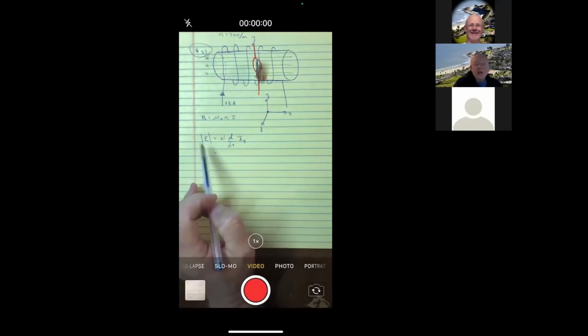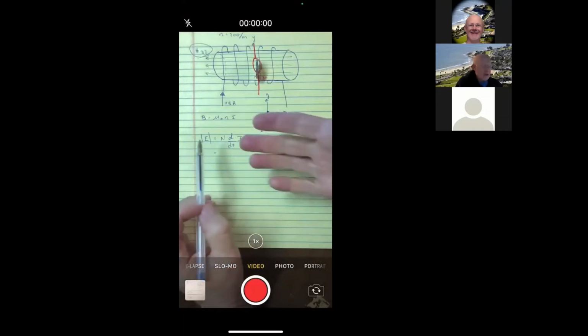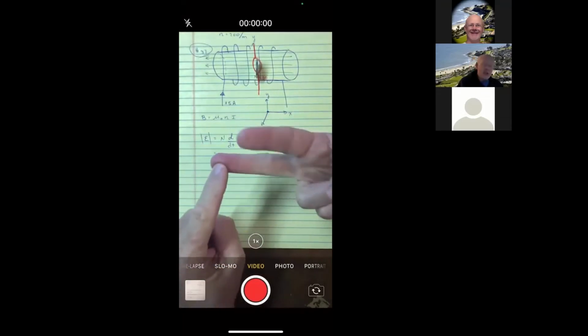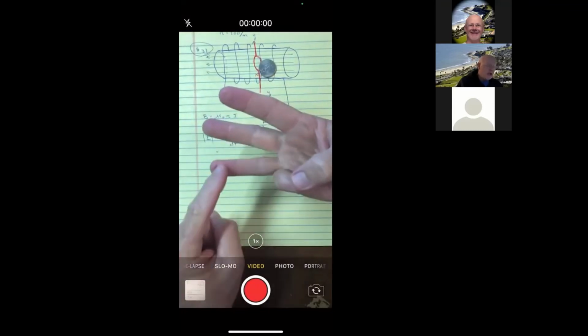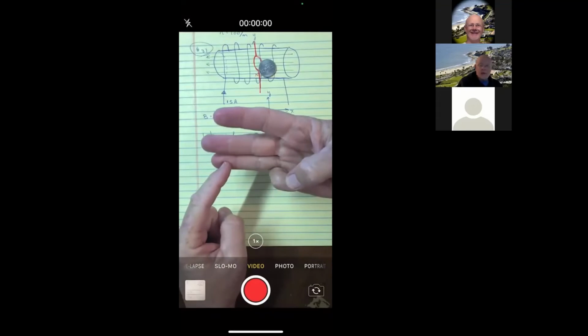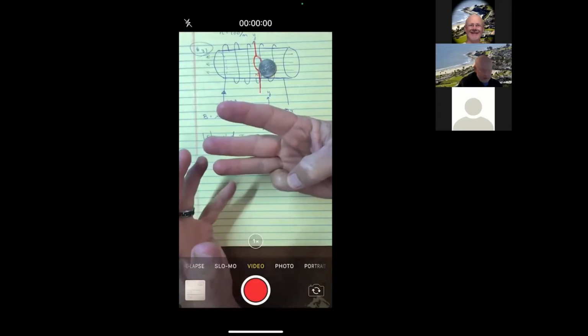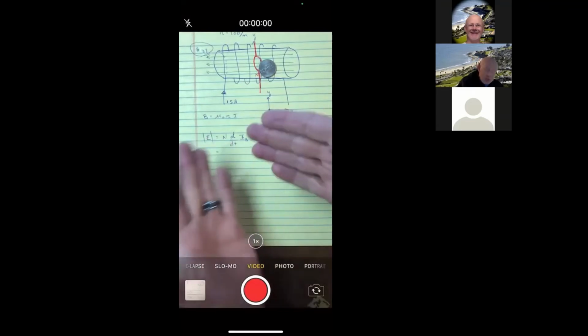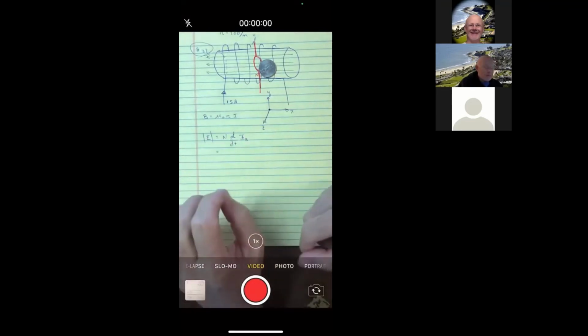And Faraday's law, just starting conceptually, says you will get an EMF if there's any change in flux. In other words, is there any change in the strength of the field? Is there any change in the area? Is there any change in the angle? And if any one of those three, or maybe two of the three, or maybe all three of the three change, then the answer is yes, there is something changing and there's going to be an EMF.